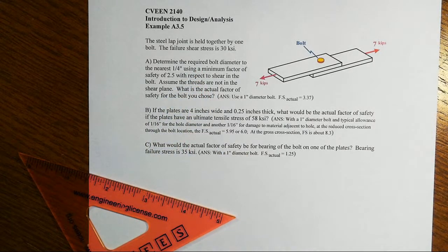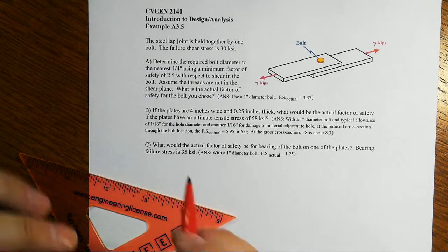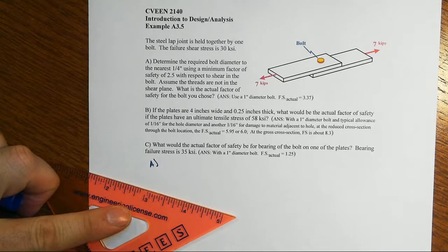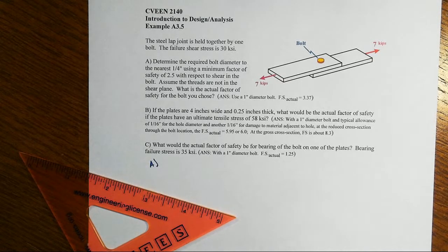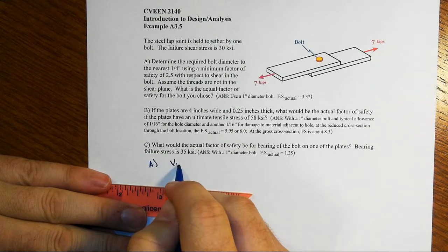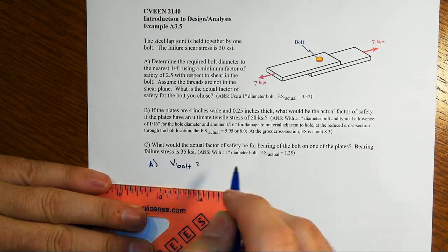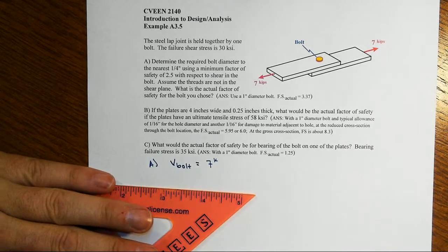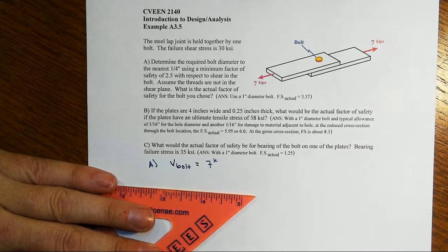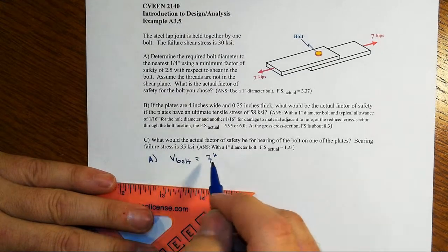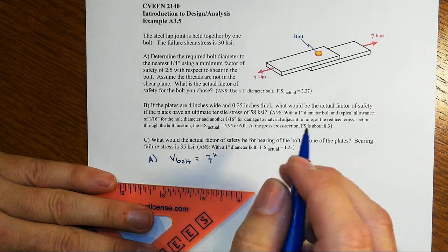Right. So let's see here. This would be part A. We've got only one bolt, so for the shear in the bolt, there's hardly any analysis to do. It's going to be 7 kips. Now if we had 2 bolts and they're arranged properly, you could assume that each bolt shares an equal amount of the shear, and therefore that would be 3.5.